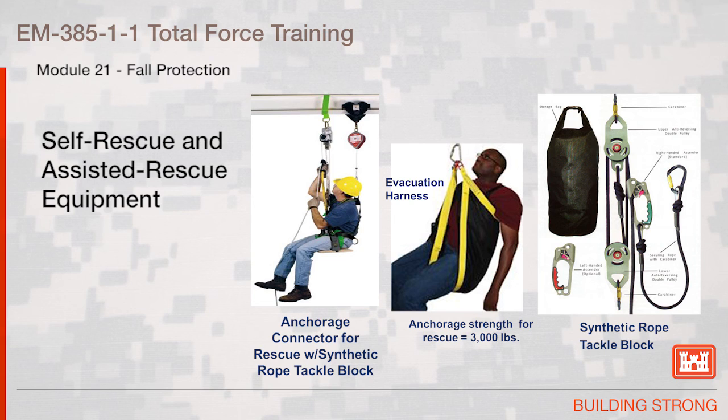Here's an example of self-rescue and assisted rescue equipment. An evacuation harness, an anchorage connector for rescue with synthetic rope tackle block. Anchorage strength required is 3,000 pounds, and on the right illustrates a synthetic rope tackle block.